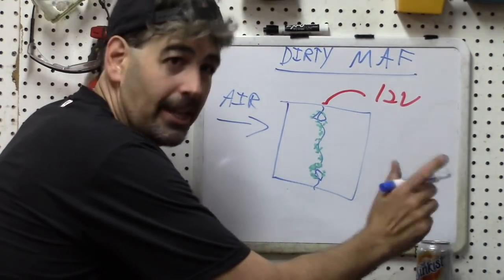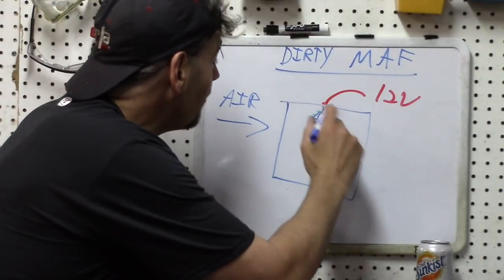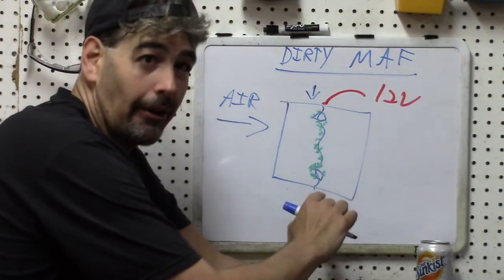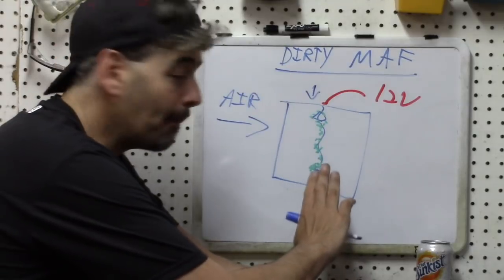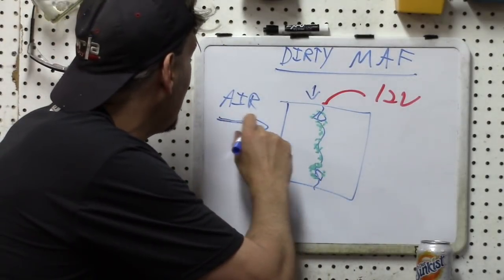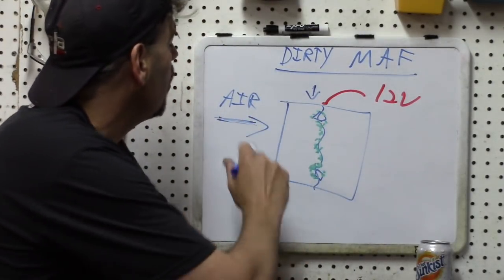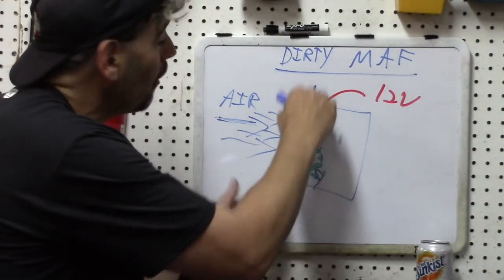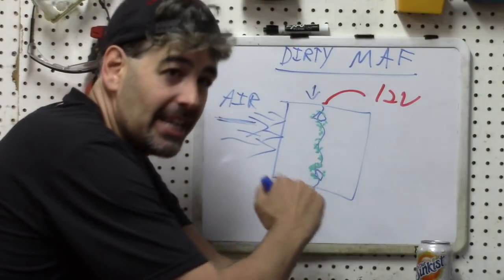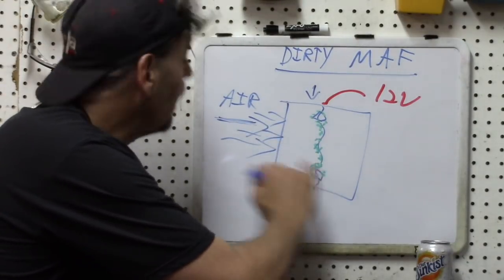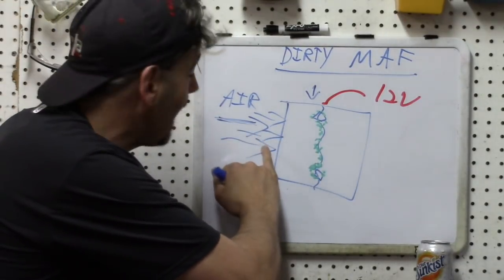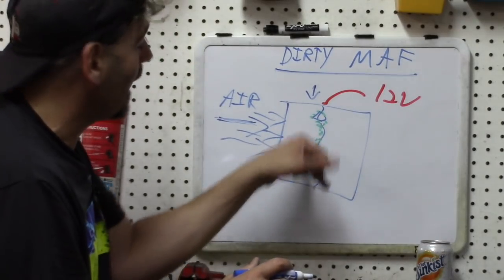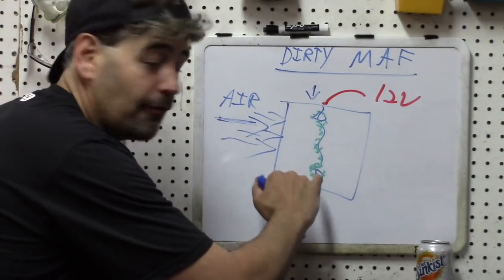If the wire is insulated, then less current will be necessary to maintain the wire temperature, and it's actually amplified as more and more air comes in. That delta of what you normally would need to heat the wire up to prevent it from cooling down here, well, that's nullified by this insulating effect.